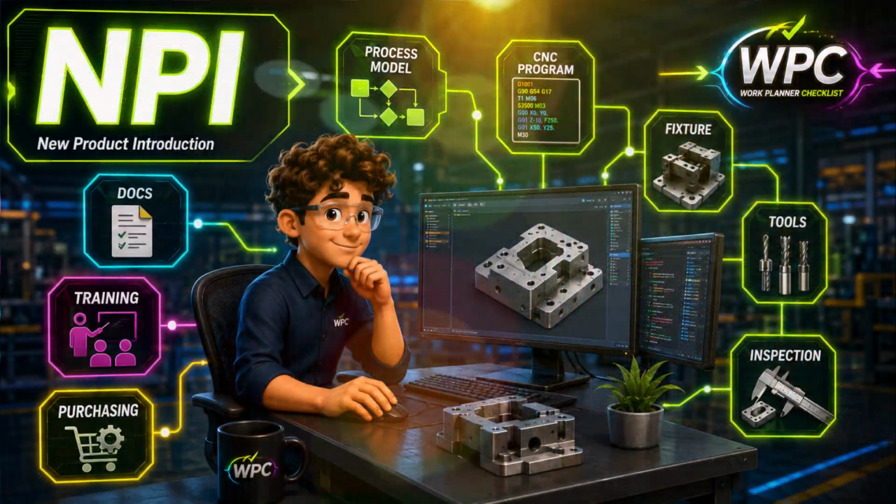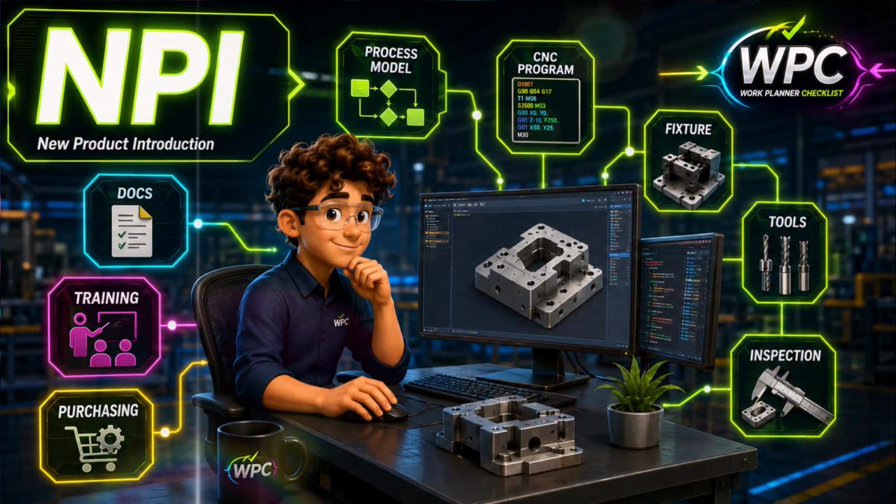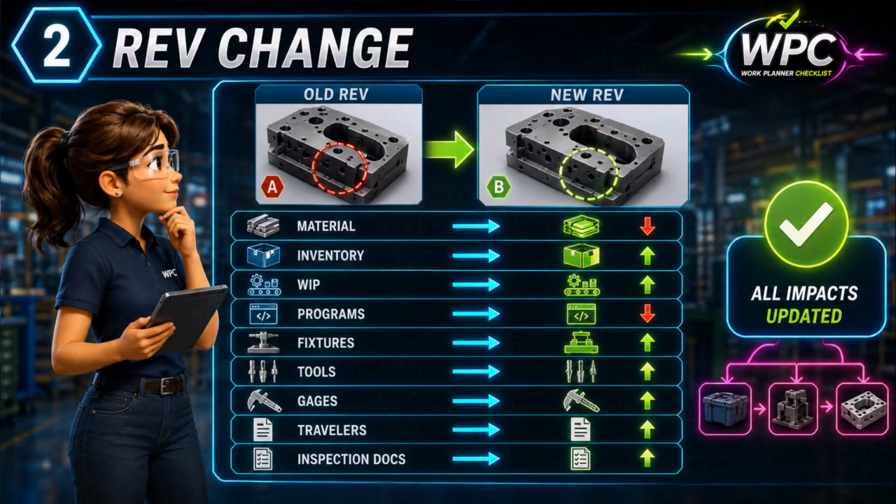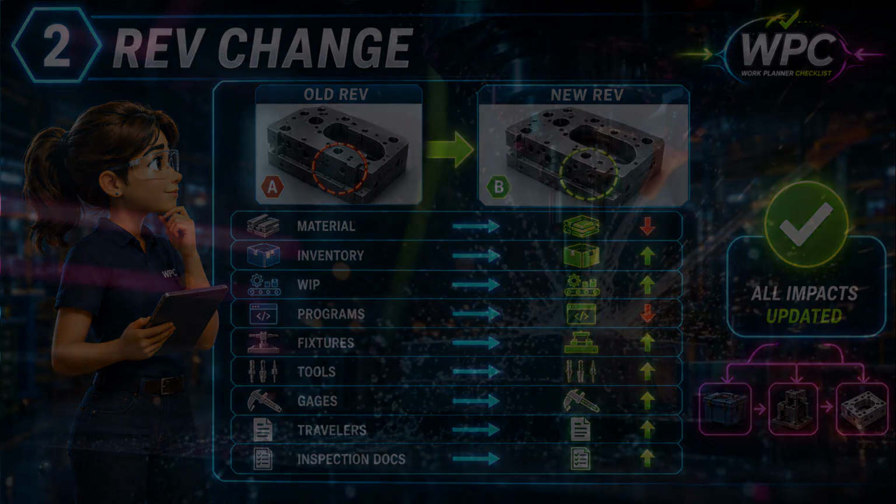The amount of planning is not the same for every order. A new product introduction, or NPI, may require a complete manufacturing plan, including process models, CNC programs, fixtures, tools, inspection methods, documentation, training, and purchasing requirements. A revision change may require the team to determine what changed and how it affects material, inventory, work in process, programs, fixtures, tools, gauges, travelers, and inspection documents.